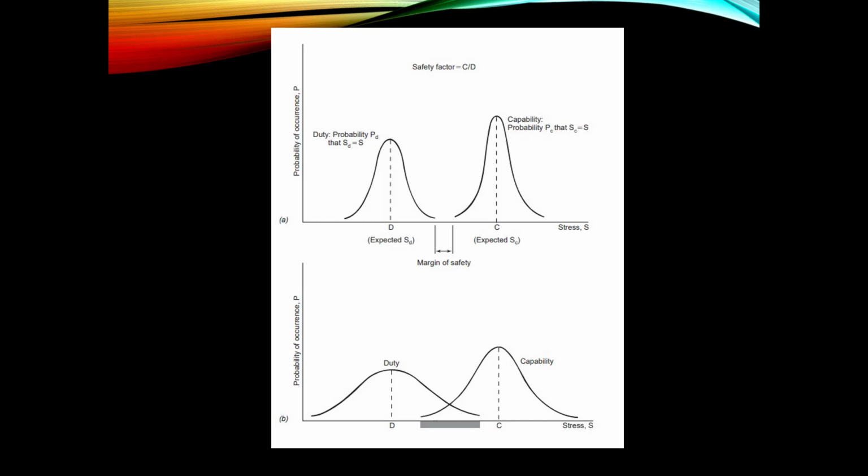So how do you handle that? What you do is you actually plan your design to be higher capacity than your highest anticipated capacity, just in case the as-built bridge is not as high as what you targeted.